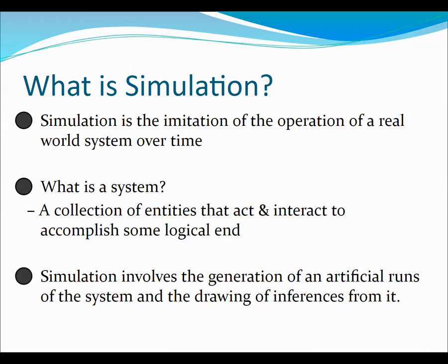Once you model the base condition and all the demands, now let's say somebody says, hey, why don't we put a roundabout in the middle? If we could, right? I don't think that location really lends itself to a roundabout because of the railway track and the limited right of way. But you could figure out, if you want to make certain improvements to that system, how would the system behave now? You can model if we could direct 5, 10, 15% of the trips from cars to bicycles, or from cars to the bus. What would happen, and how much improvement could we make?